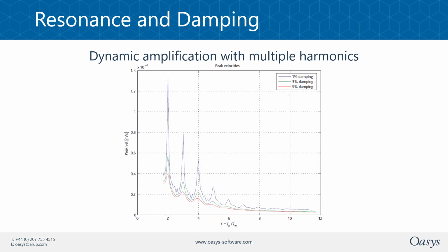So, as the fundamentals need to be above the walking speed, let's remove that resonance and look in more detail at the harmonics. Note that the second, third, and fourth harmonics are resonated, but also the fifth and sixth and so on to a diminishing amount. We don't calculate these ones because as human walking speeds are not that constant, it's very difficult to resonate with the higher frequencies. And in some situations, we might only take the first 1 or 2 or 3 harmonics. It depends. The design guide will state how many harmonics you need to look at for particular situations.